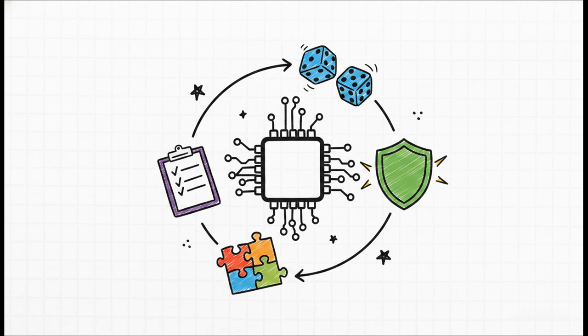It brought a whole suite of superpowers to verification. It brought object-oriented programming to hardware testing, letting engineers build these massive reusable test environments. It features built-in randomization to automatically throw thousands of random constraints at a design just to try and break it. It uses assertions to continuously monitor the design and flag if any rules are violated. It provides interfaces to cleanly bundle connections together. And it uses functional coverage to actually measure, mathematically, if your tests have hit every possible scenario.